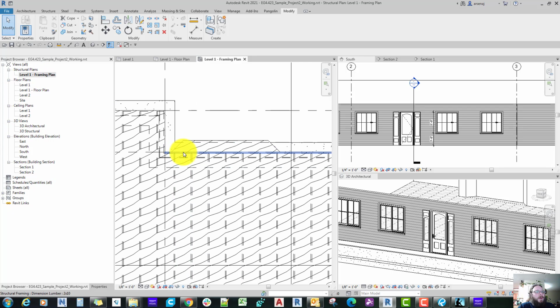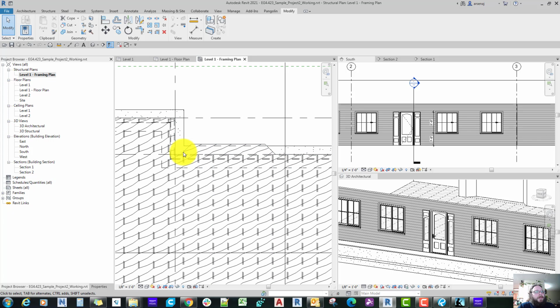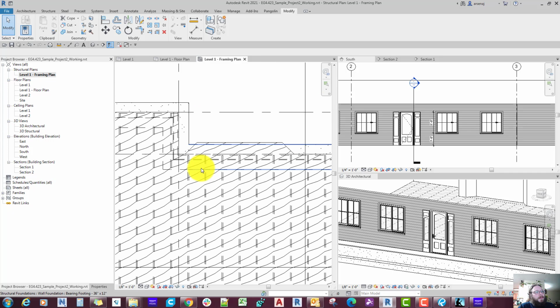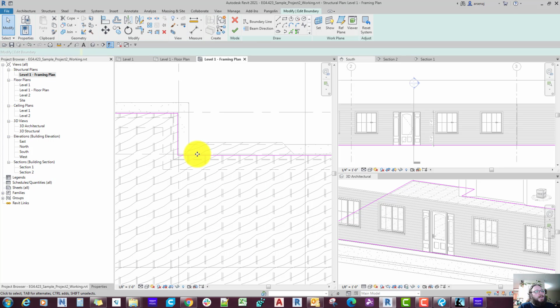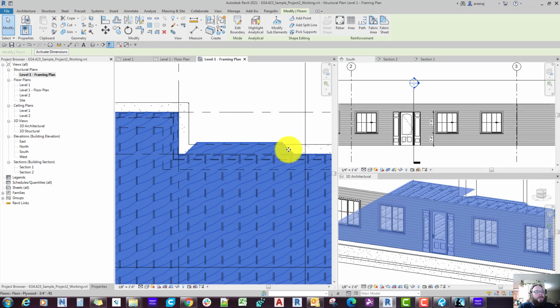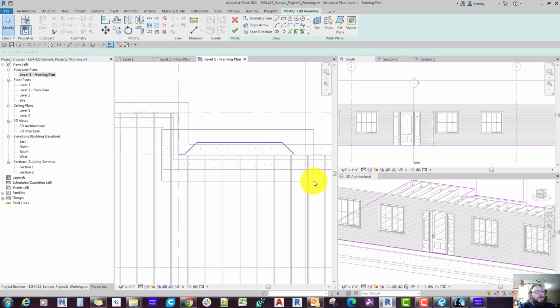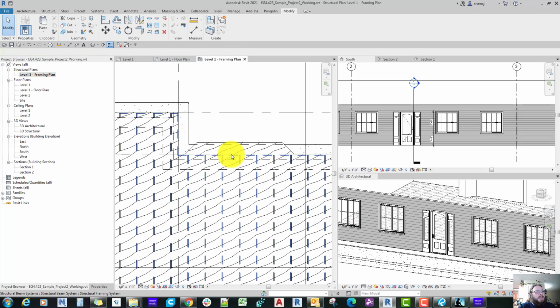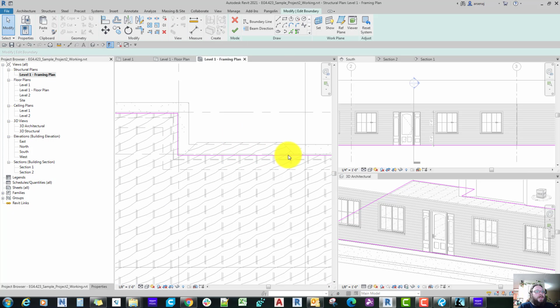So we'll do all of this. We'll have to do all of this stuff, adjust the footing, and everything else. So let's highlight the beam system here. And actually, here's a nice way to do this. So we already know that we've got this profile, so we can copy these lines here from the floor and then paste them into our boundary for our beams. So I'm going to actually use this to trim and then paste in.